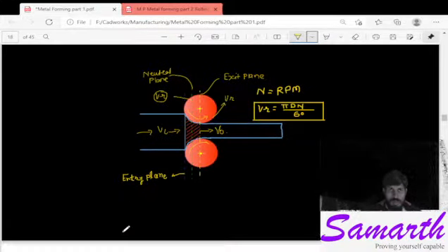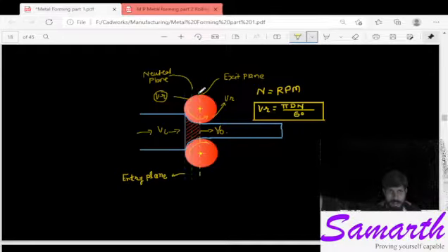Here I have shown you the exit plane. This vertical yellow line or shaded portion is the area where the force will be experienced, and the very first dotted line you can see is the entry plane. The middle one is the neutral plane, where the velocity of the sheet equals the velocity of the roller.